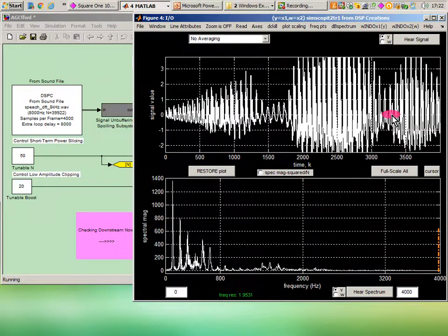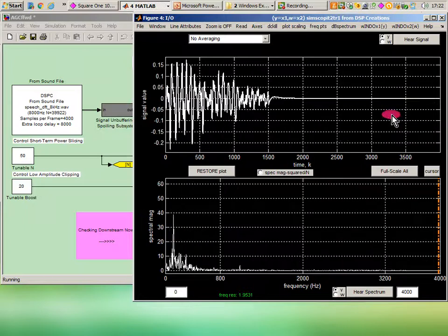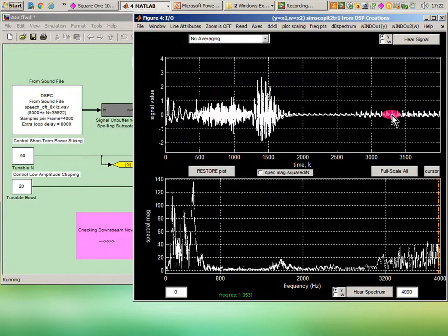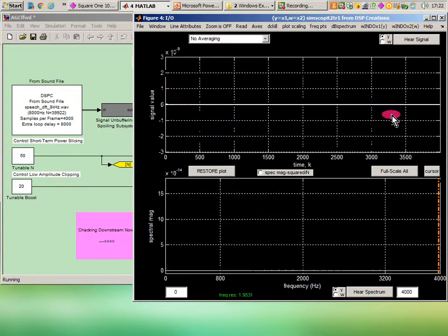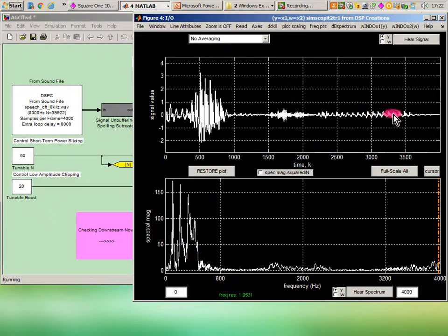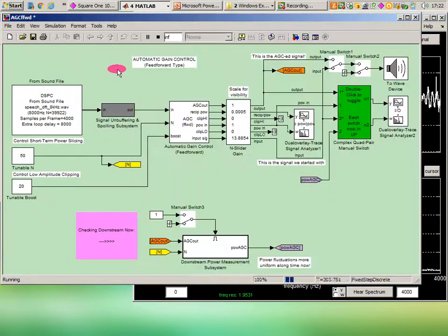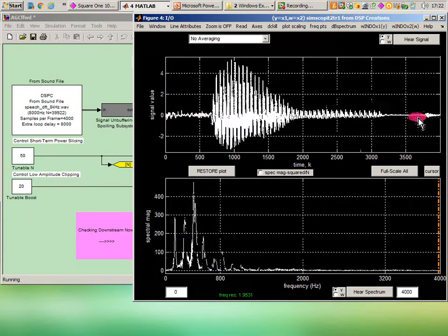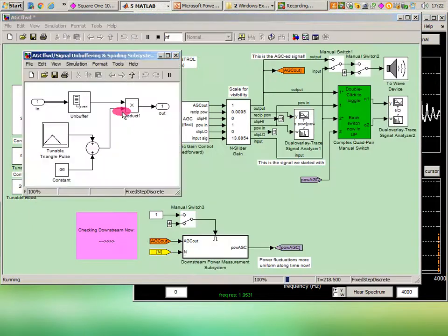Well, fading is an important effect which plagues a lot of communication systems, particularly voice communications. People like amateur radio operators and so on, who have signals going through atmospheric effects which cause great problems for them, and AGC comes to their rescue sometimes. Of course, true fading is very complex and random and all the rest of it, and so what we've got here imposed on our waveform is not only the sporadic nature, but also some weighting which has been put in here, and I'll show you what I've done.